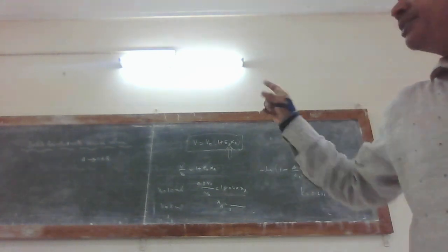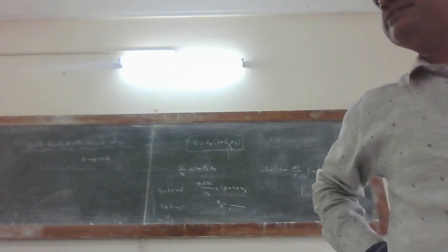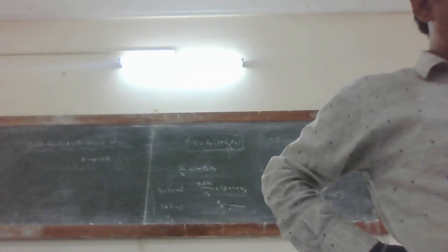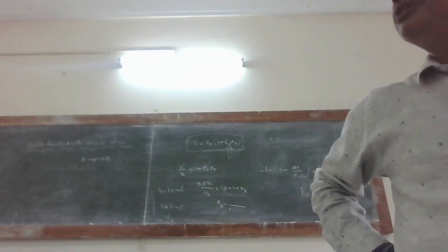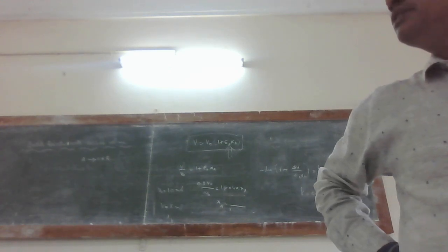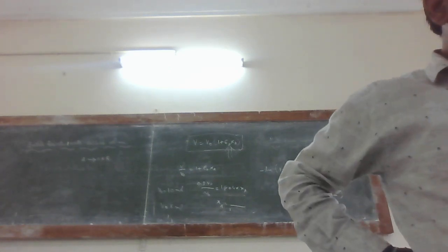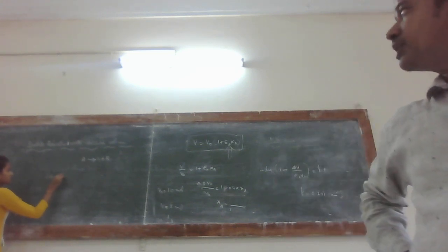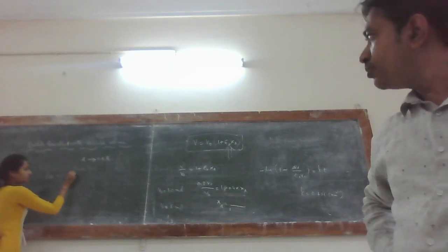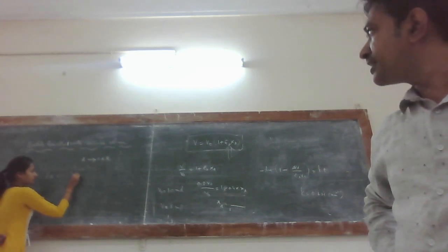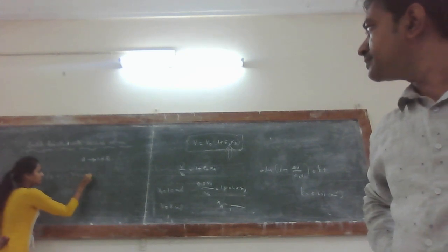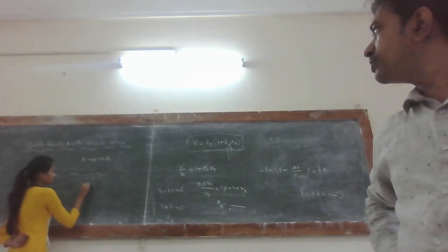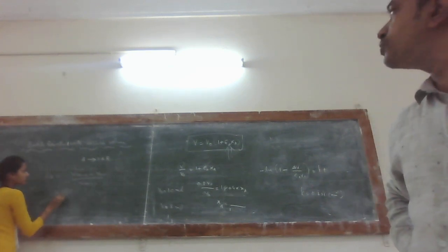Priyanka, can you go and find out epsilon A for this case? A gives 2.5 R. Epsilon A is equal to, write the formula: volume at 100% conversion, V at XA equal to 1, minus V at XA equal to 0, divided by V at XA equal to 0. Now what is the equation given? A gives 2.5 R.